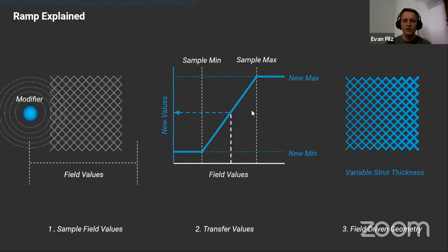And you'll notice that we flatten off the top and bottom here, so it's not an indefinite interpolation where you define the maximum and minimum values. If you're any closer than, say, 1 millimeter to the part, that entire region will be 1 millimeter thick. Or if you're any further than 10 millimeters away from your part, that region will be your maximum thickness. It won't continue on. It's not an infinite growth. So what that looks like here is where we have the thin structure, and it radiates outwards according to the field of that sphere to get our thickness.